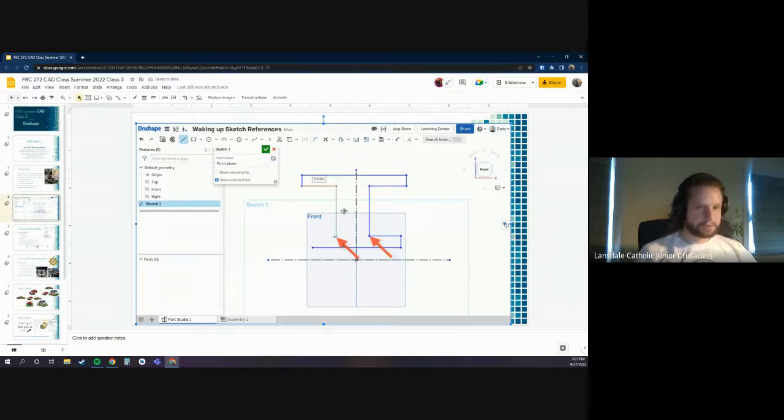It might be a little bit hard to see, but there are these little tiny yellow dotted lines that appear. And it's also creating implied vertical and horizontal constraints for some of those things. And if you do want to make an implied constraint, you can go over to a point and kind of force it to imply a constraint. And that's what's going on in this image here.